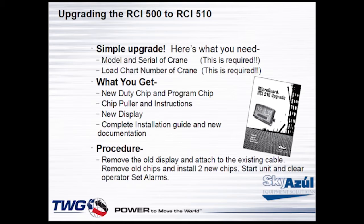So here's what you get. It's a really simple upgrade. What you need for Brian is the model and serial of the crane, the load chart number of the crane, and possibly a shot of the duty chips. If you can get that for him, that will really be helpful. What you're gonna get is a new duty chip and a new program chip, a chip puller, and instructions. That's where you get your chip puller right there, just buy a kit.